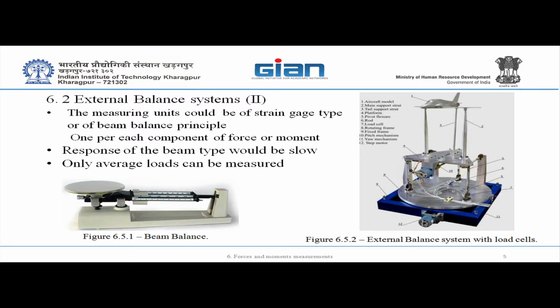Depends on what system you have. Probably use it both, just to move the model, just for moving. Pitch up, pitch and yaw. This kind of arrangement was for a long time back. It's not an issue. The strain gauges will be inside this sting which is holding the model. We'll talk about it, we'll show it later. Strain gauge will be within the model.